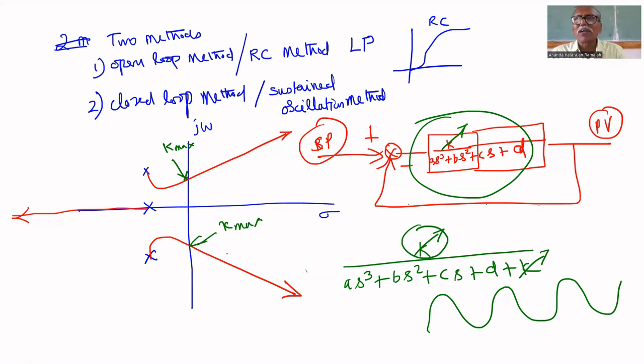In the lab, what you are doing is, maybe here means you said unstable, why the answer is not correct. Sometimes here means no sustained oscillation. It is before that j omega axis, so no sustained oscillation. Initially, small oscillation you might have seen, after that it settled. If it is here, it goes to unstable, either to cutoff or saturation.